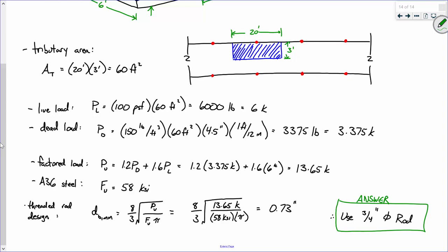So, yes, sir. If you're going to have the 1.75, I would bump it up to 7/8, because that's probably what's going to be available. But let's also not live in the ivory tower. If my local supplier doesn't have any 7/8 inch, I'll bump it up to the 1 inch. Let's also be clear, there's reality going on too. Maybe Huntington Steel doesn't have any 7/8 inch diameter rods. Maybe they've only got 1 inch, and that's what I'm going with.